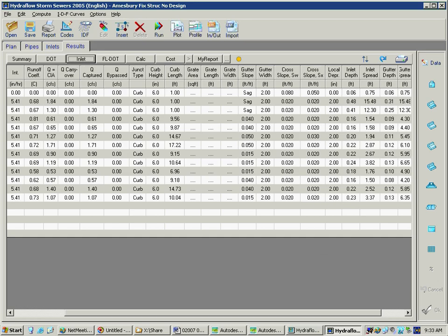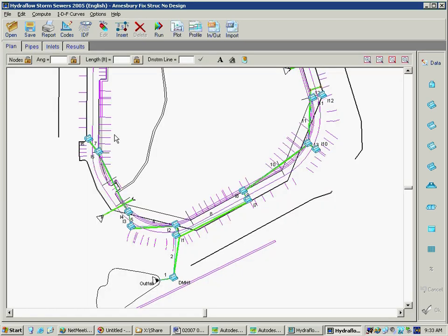Something that I've noticed too is I like to double click a lot of things. If you double click on these pipes, it will open this dialog box. But you've got to be really cautious because it has a tendency to want to rotate the structures, and it can rotate your entire line. If you do that, just come up here and hit lock on all your structures.